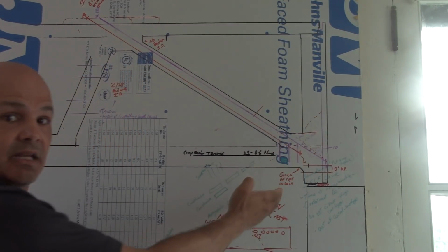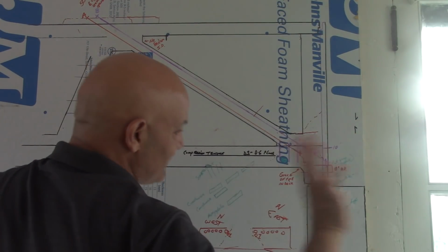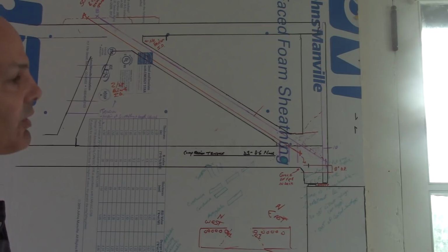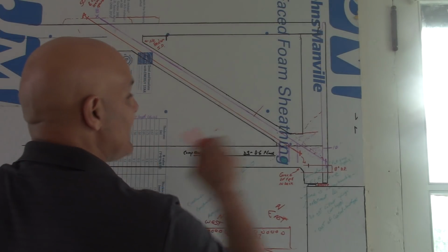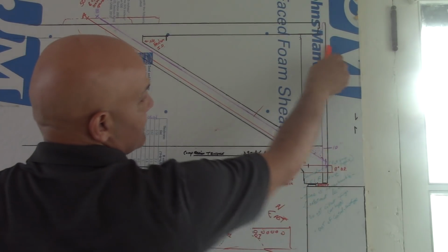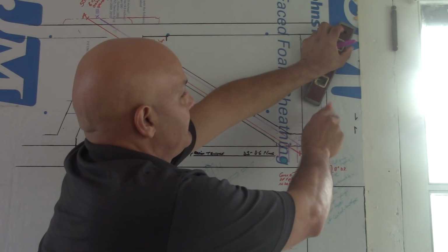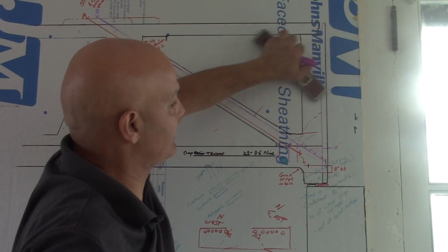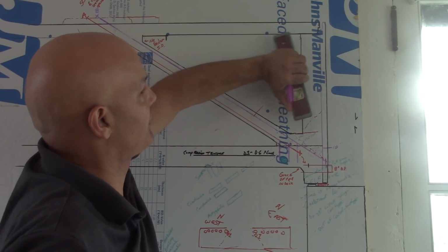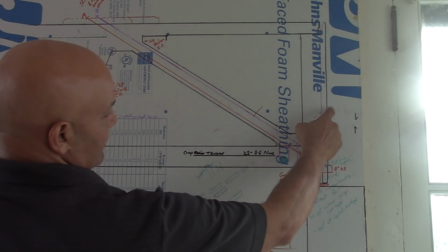Into number 12's column. So you'd see a crack where? Up here somewhere. Don't get excited, there is a crack up there somewhere. That's during the braking. That's not during, it's when the bridge does a force like this. When it does this, kicking over, that's this break. And then it's going to come back the other direction because it's tied to post-tension cables at the top. So don't get excited about this one little break up there.